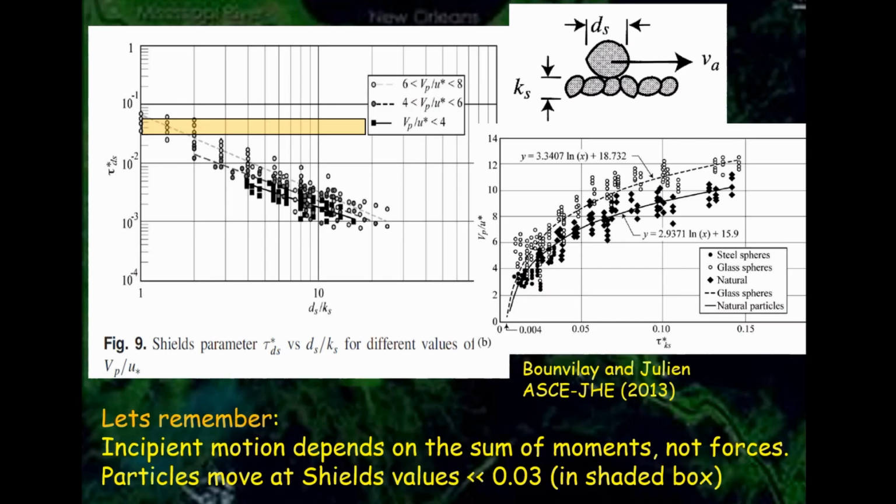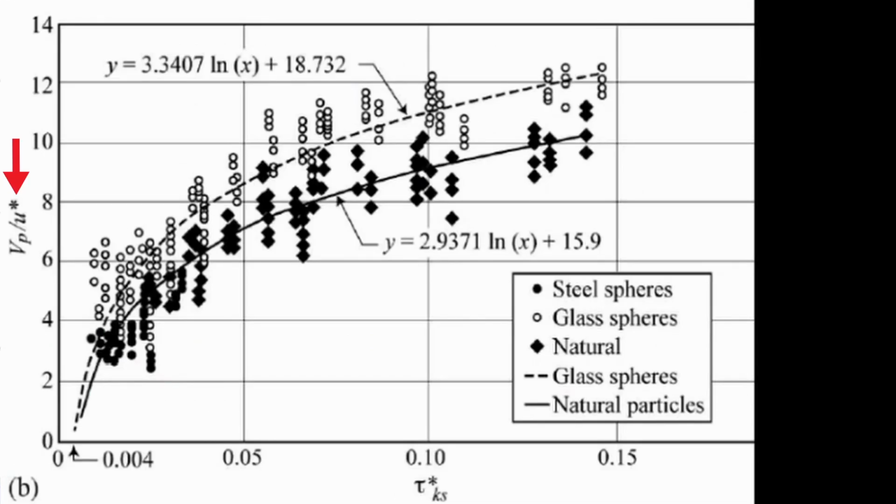Another thing that we found, and that's why experimental research is really interesting. I give you one example here, but it could be about all kinds of other parameters that we assume blindly, and they could be revisited. Interestingly, if you want to get the velocity of the particle, I normalize by U star, which is a hydraulic parameter that is constant. But VP is my velocity of the particle. I get better agreement, and that's the graph here, if I take the Shields parameter of the particle down below, than the Shields parameter of the particle rolling on top. Does it make sense? Yeah.